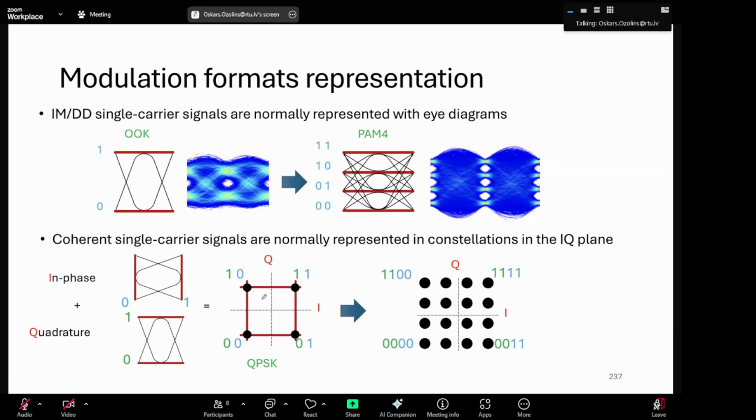So you increase the capacity by a factor of 2 again. And that's why it's easy, for example, to get on smaller band, or on the same bandwidth, more capacity, like it's done with PAM. But in coherent systems, you have another degree of freedom, because you have in phase and quadrature. That gives you another factor of 2.